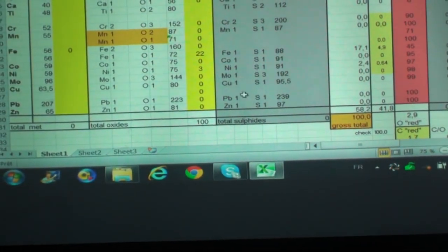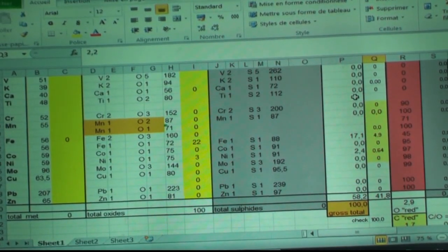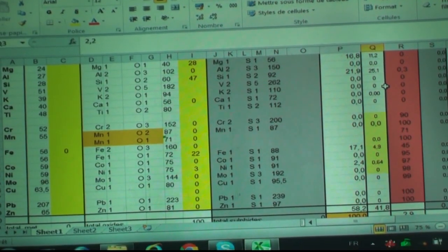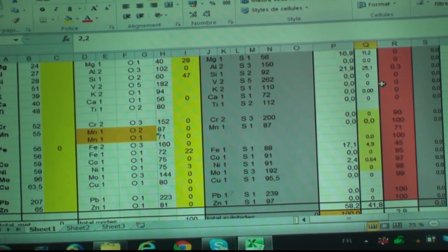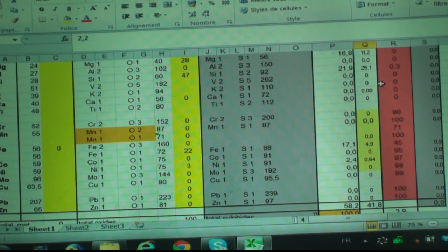The rotary kiln's main purpose is the reduction of the Fe and the heating, both. Preheating to 800 degrees, but when you preheat Fe2O3 to 800 degrees, you will reduce it to FeO with coal, with a reducer.